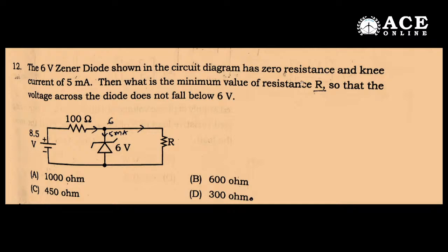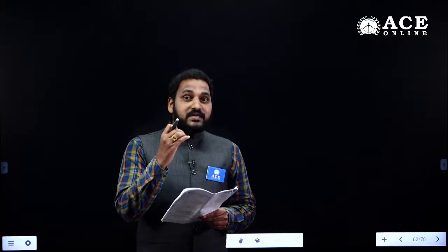Here the resistance R is nothing but the load resistance RL. It is saying that the load voltage or output regulated voltage should not drop, meaning the circuit has to work as a voltage regulator. How long can the device act as a regulator? As long as the Zener diode is operating in the reverse conduction state. This is a key point.